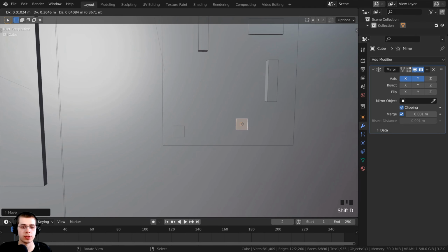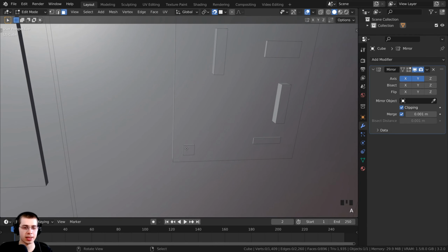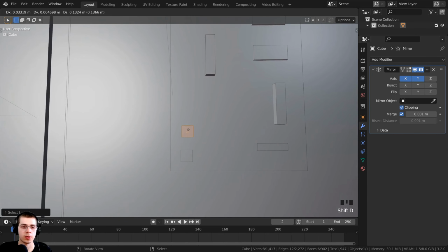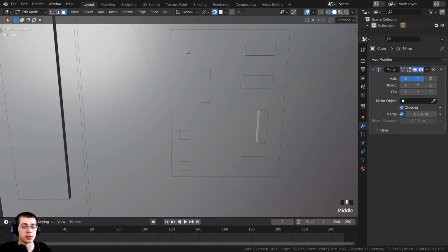And then I can press Shift D to duplicate. Let's stick one there, and let's scale this out on the Y-axis and just kind of scale it down, just kind of bring it over and stick it right about there, maybe scale it down just a little bit. And then I also want to add another one of these squares, so I'll press A to deselect, press the L key to select the linked vertices, and I'll press Shift D to duplicate, and let's stick that there. And then I also want to add some circular buttons.